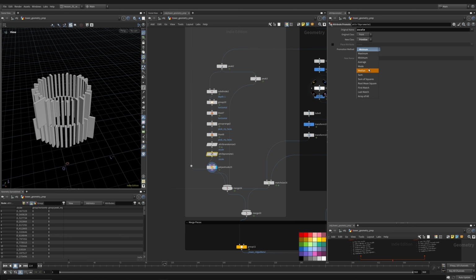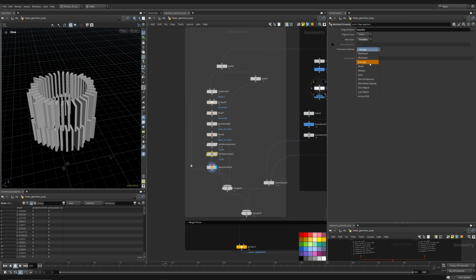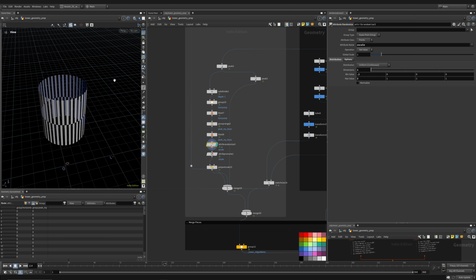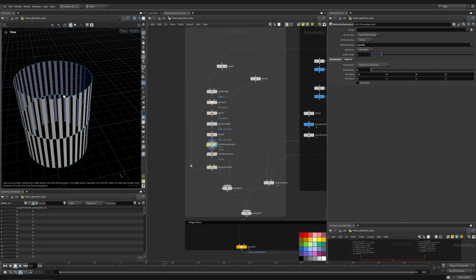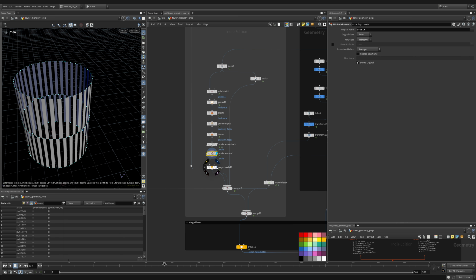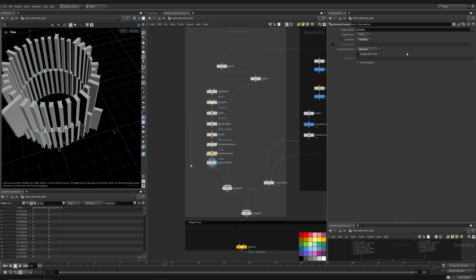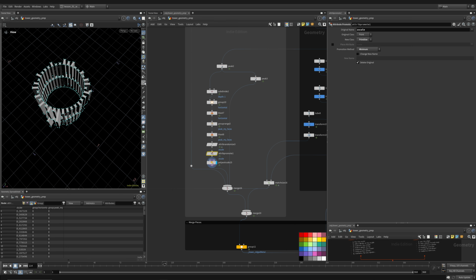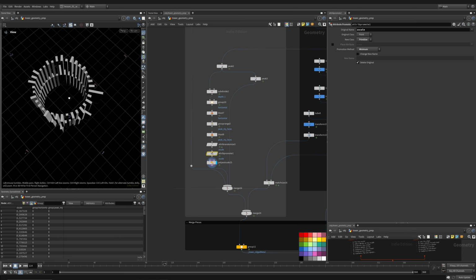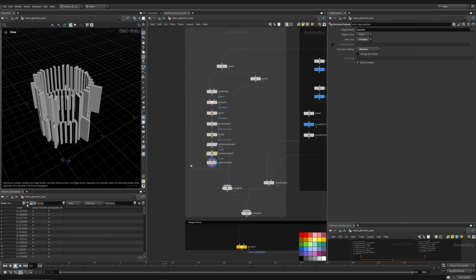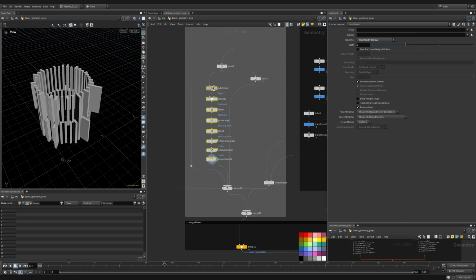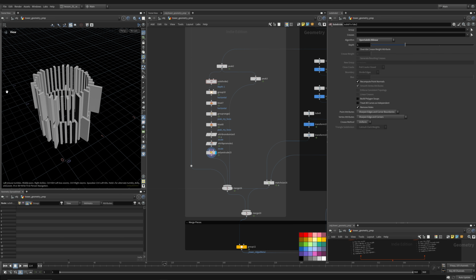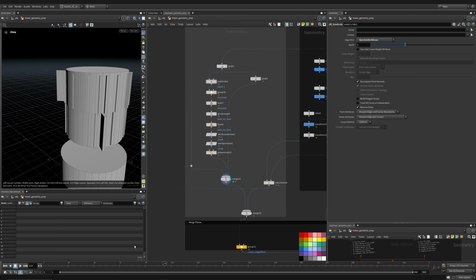And we can promote in multiple ways. This would take the average of all of these points. They each get their own random p-scale, or z-scale, excuse me, and this is going to average those when it promotes it. Or I could say take the minimum or take the maximum. Also an important part in Houdini in general, and not just modeling, is being able to move attributes from points to primitives to details, and back and forth, and actually know what you're using the attributes for. So this is kind of cool.